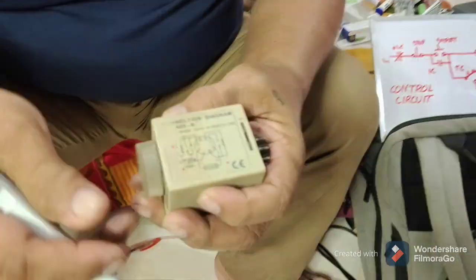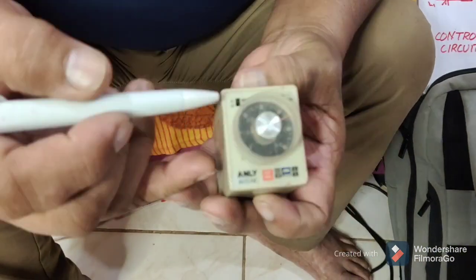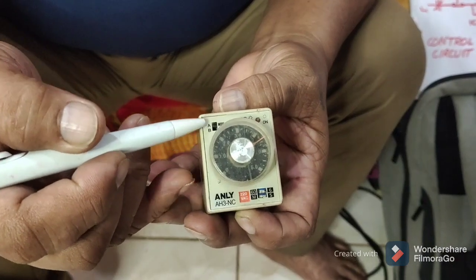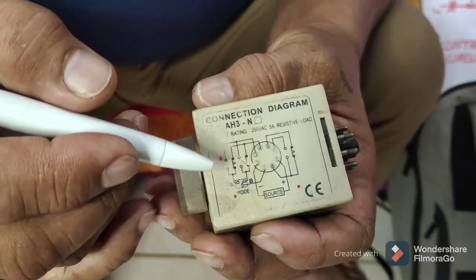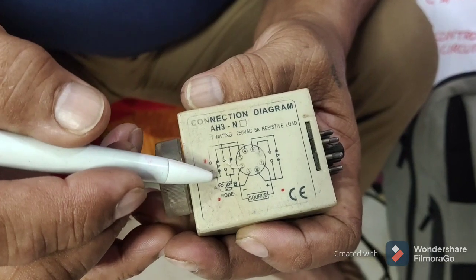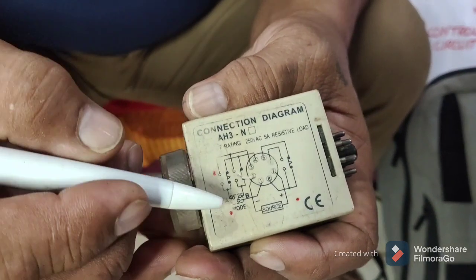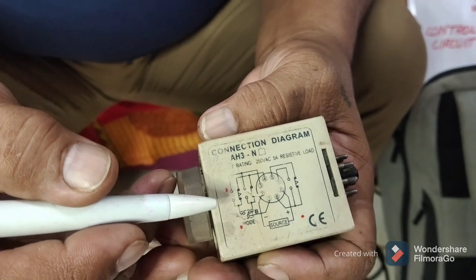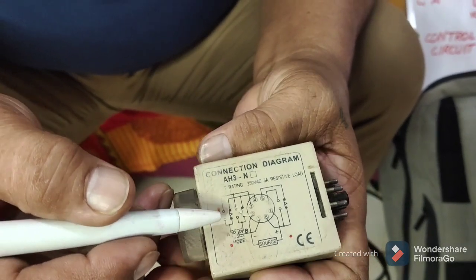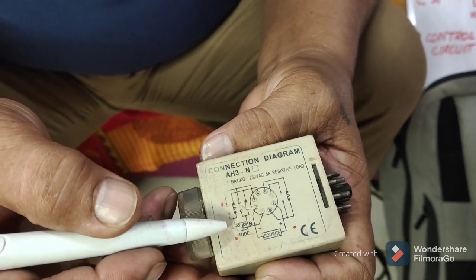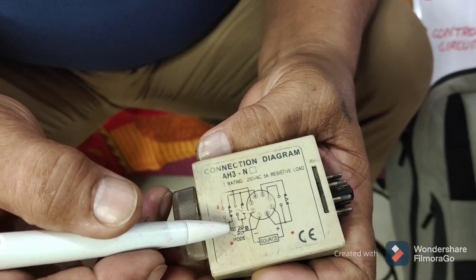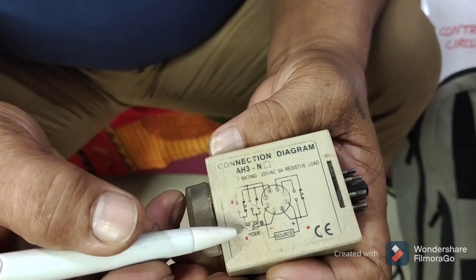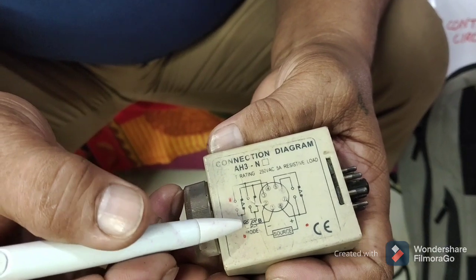You will observe that there is mode here, there is mode A and B. Okay? Mode A and B. Now, where will you use the normally open, or shall we say an instantaneous contact or instant contact of your timer? So if you want to use an instantaneous contact or instant contact for maintaining contact, what you are going to do is switch this to